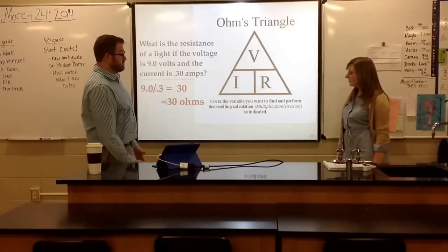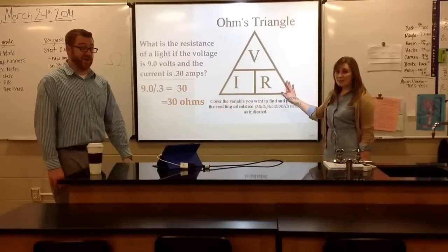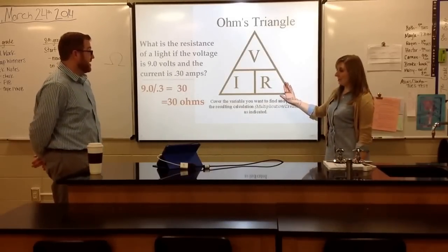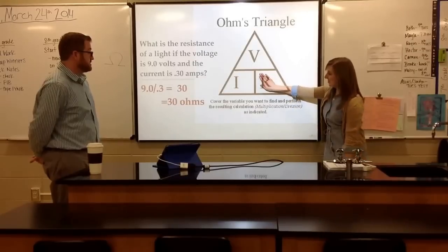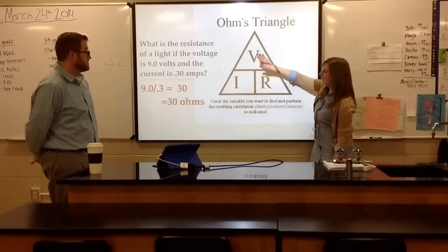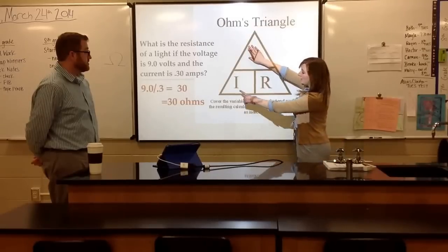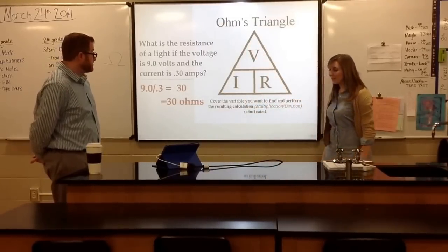So you don't need to memorize the formula, just memorize the triangle. I would definitely write this in your notebook right now. Make sure you understand. If you want to solve for resistance, just cover that up. Divide voltage by current. If you want to find voltage, you're going to multiply current by resistance. Pretty slick.